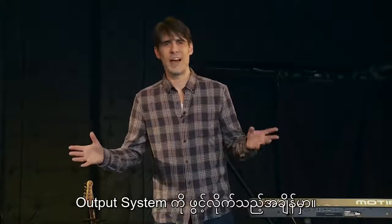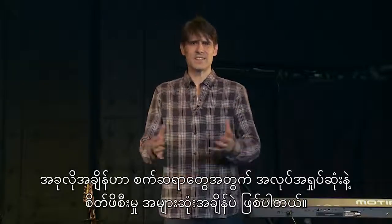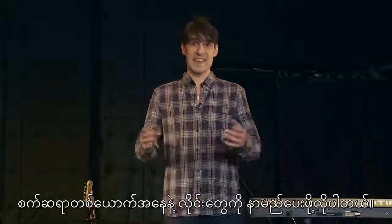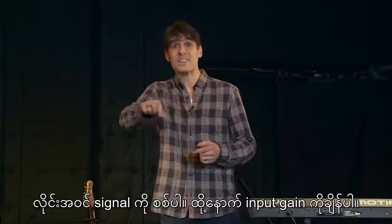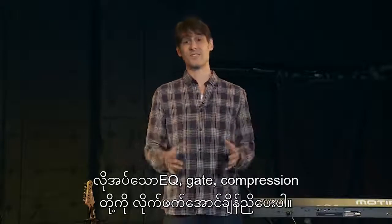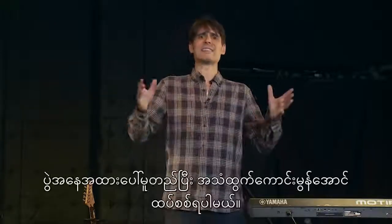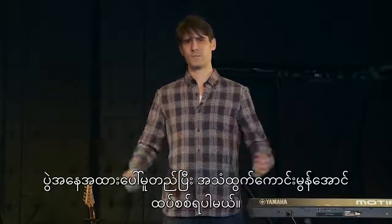Once you've tuned your output system, it's time to get ready for the band sound check. This is often the busiest and most pressured time for a sound engineer. He needs to name the channels, check the inputs are present, set the input gain, adjust the EQ, the gate, the compression to suit each instrument, voice and microphone. And he has to make sure everything sounds suitable for the surrounding environment. The larger the band, the longer it takes.